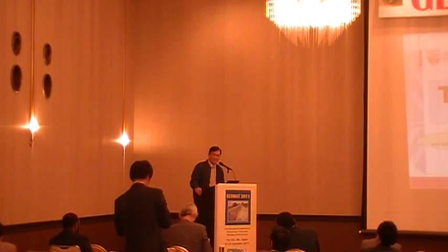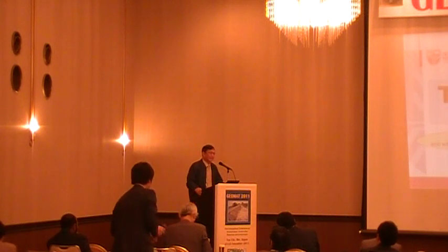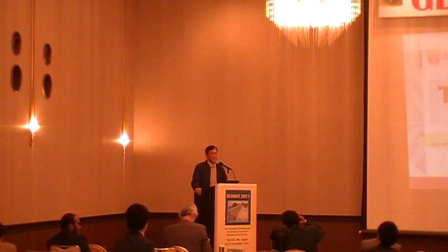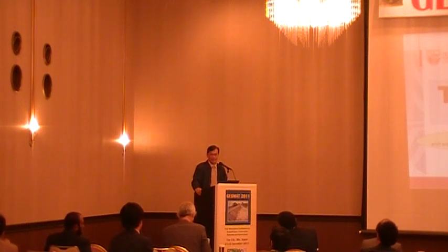You see the live pole? Yeah. Okay. When our live pole in the short term acts as a shear pile, because we can plant it, we can insert it down maybe up to 2 meters down. So over time it will grow roots, so that will give you added reinforcement. And also, as we know, because it is living, it takes away water from the soil, and that will actually increase the suction. So you have 3 benefits.